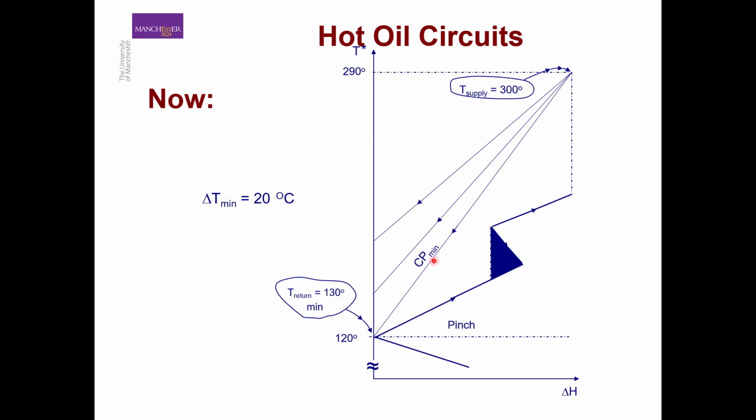So ideally, as I said, we always want the return temperature of the oil to be at the pinch temperature, but unfortunately, it is not always possible. And we can see on the next slide what the scenarios are when it is not possible.